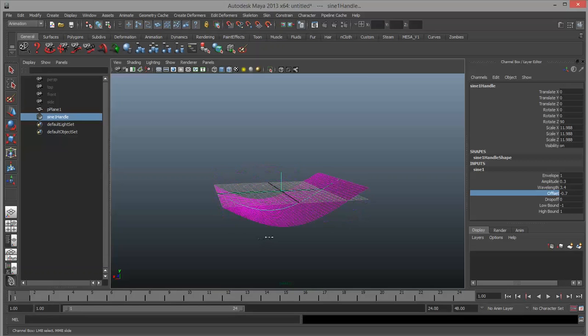Now if we did want this to be like a flapping flag, this wouldn't do because both sides are moving, and a flapping flag would have to be fixed on one end. For that, we've got this drop off here. So if I turn that up, do offset, now you can see both ends are held steady while the center is the only thing that moves.